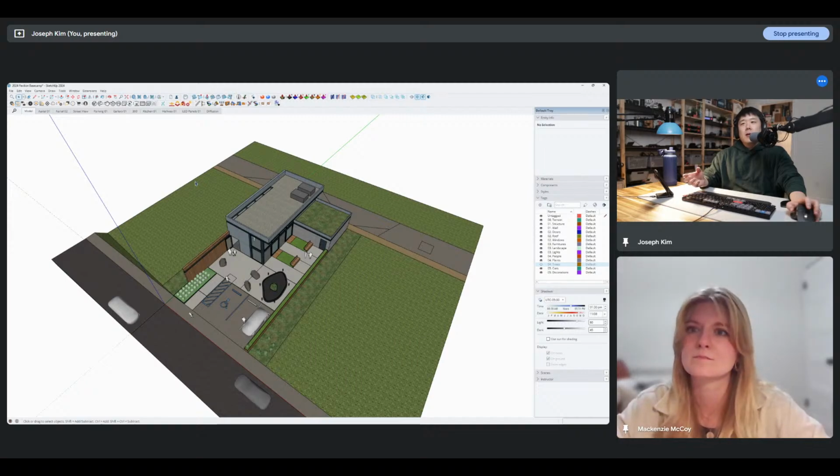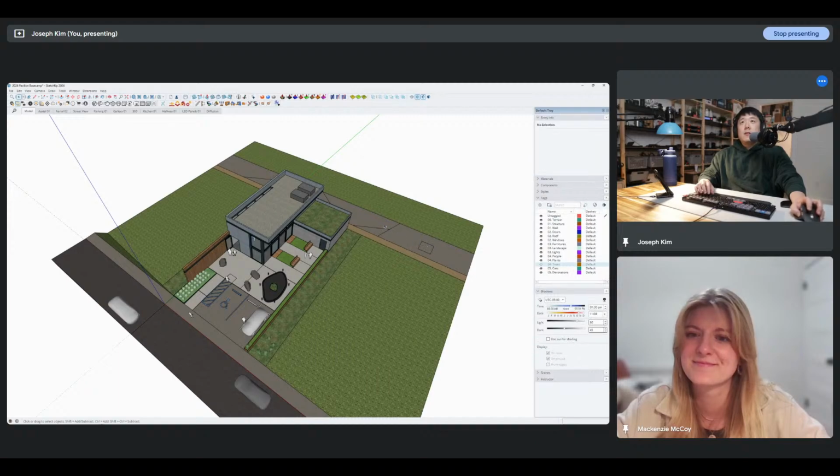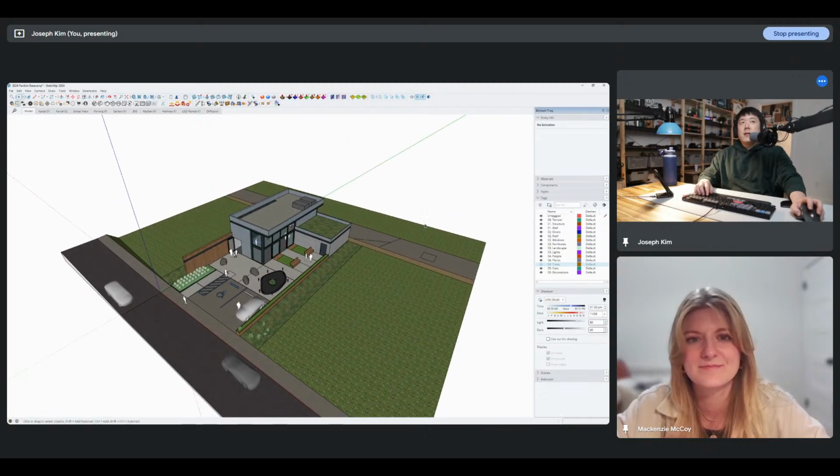You can control that later on. That's a more advanced feature of scenes, which is available under the scenes tab. But by default, let's say I rotate it a little bit and then right click and update, that means it is going to come back to that rotated scene rather than the other one that I had saved. And currently, that is not undoable. I cannot undo what's been updated to the scene, so be careful when you make that kind of change.